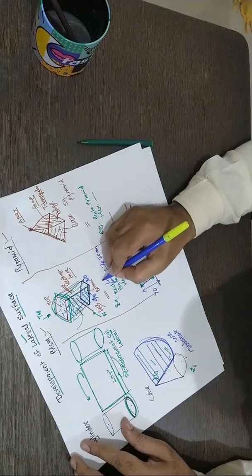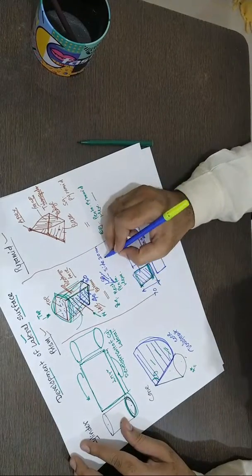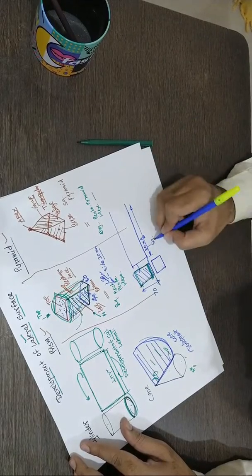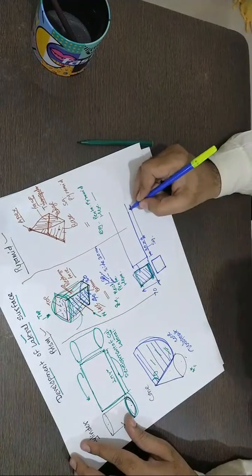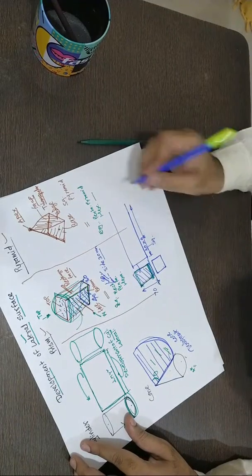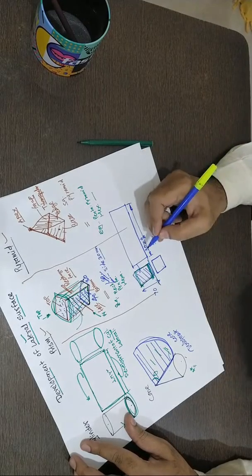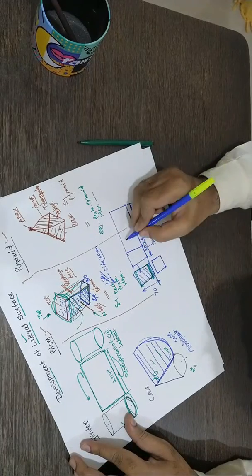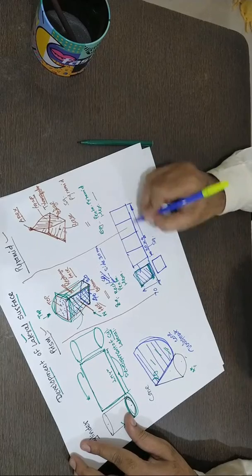To make it simple, I'll say a square. Okay, so a square prism, side 30 mm. So it will take square base side 30 into 4, as of course the number of base edges. So it will be the total length of your development. So just add those edges. So you can say this 130, 60, 90, and the last one, this edge.